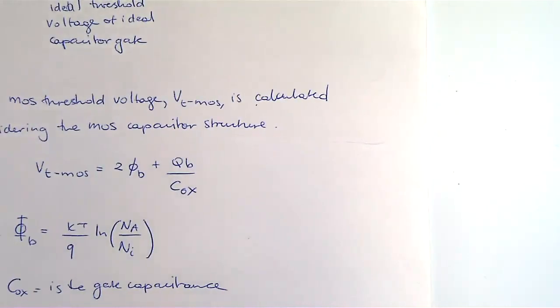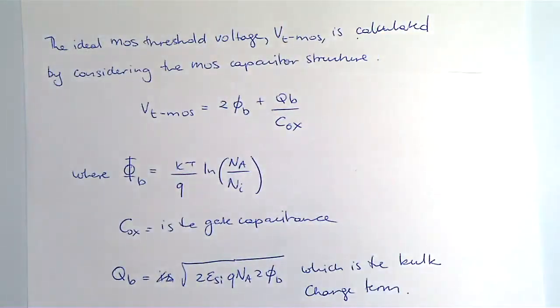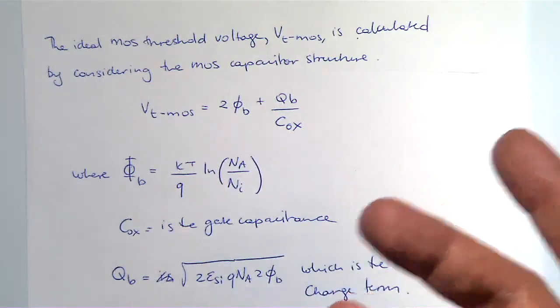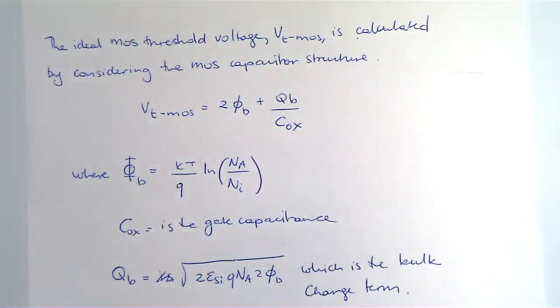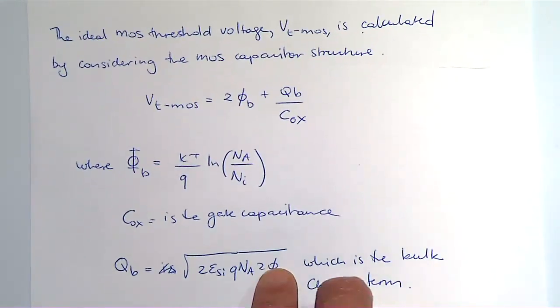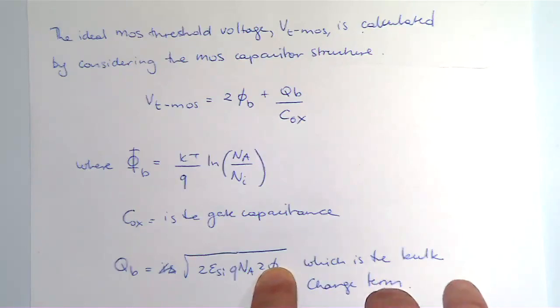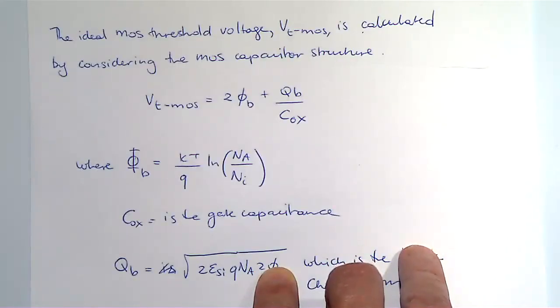The reason why I'm going through this is to show you that there's this concept of threshold voltage which we've described, but also that threshold voltage depends, and as we'll show, on the substrate or the source to body voltage, or source to substrate voltage.